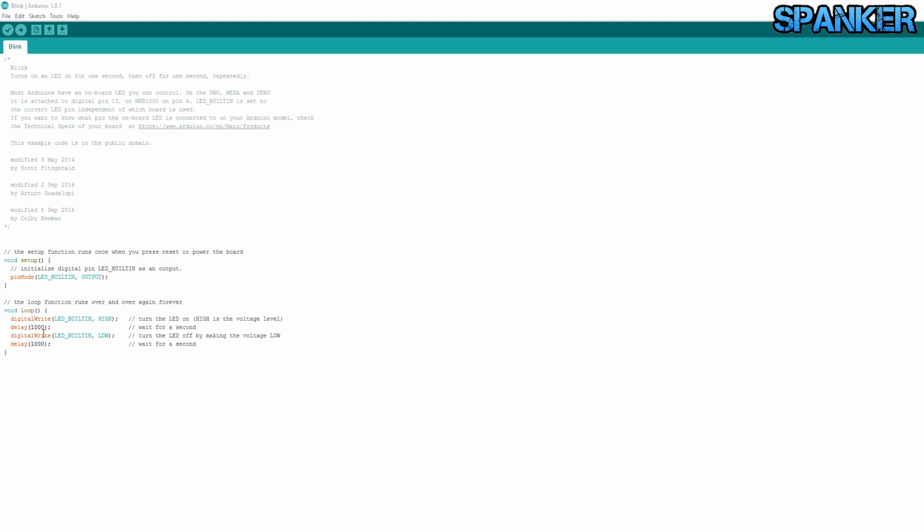So it's digital write and it's delayed for 1000 milliseconds. What I'm going to do is change that to 2000 milliseconds. So it's going to come on, stay on for 2 seconds, and then go off. But then I'll only want it to wait for 100 milliseconds. So we're changing what we want that LED to do. What I would then do now is up here, top left hand corner, upload.